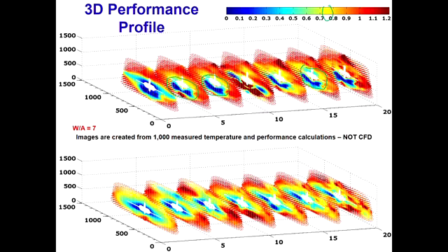By the way, this is an upper bundle in the upper half and a lower bundle in the lower half. So this is what air binding looks like in different condensers, and I've shown you air binding in two different condenser designs, and we'll talk about how to get rid of those airbound zones later on in the talk. But this is what air binding looks like.